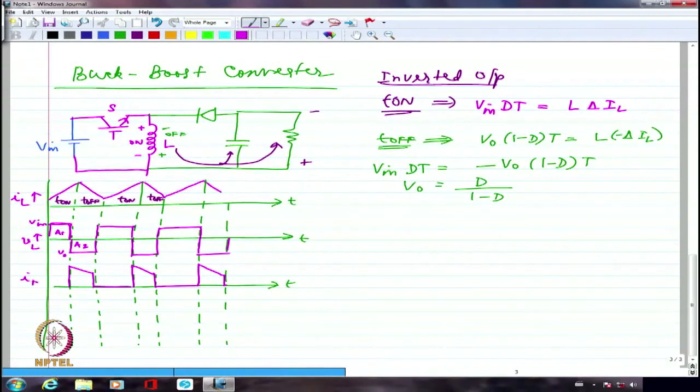And the diode current, if I try to look at the average value, that will be my I naught. So I have to draw I naught somewhat like this. This is probably my I naught value. Please note again, this is averaged over a complete period T. So it will definitely be less than even this value, because it is averaged over the entire period. So this is going to be I naught, from which I should be able to draw the capacitance current.